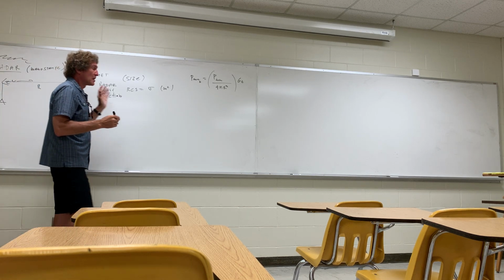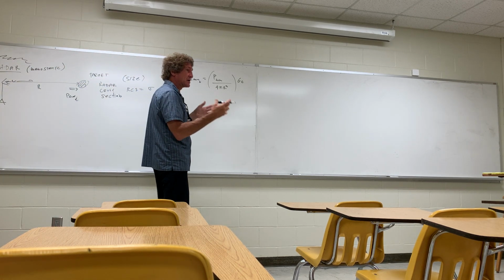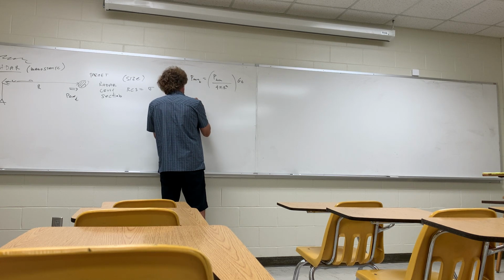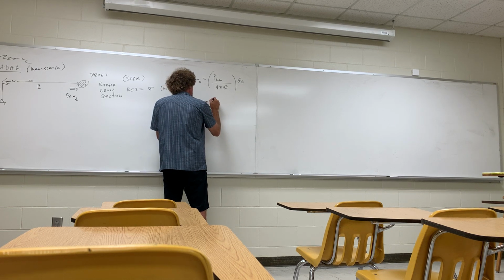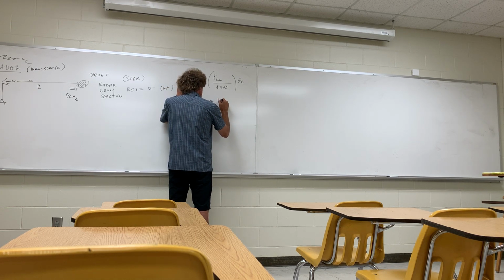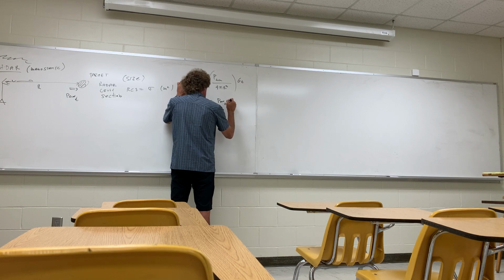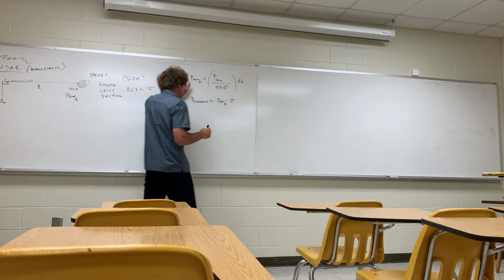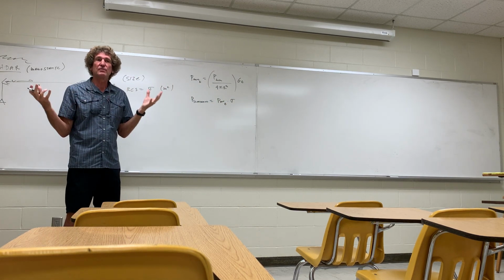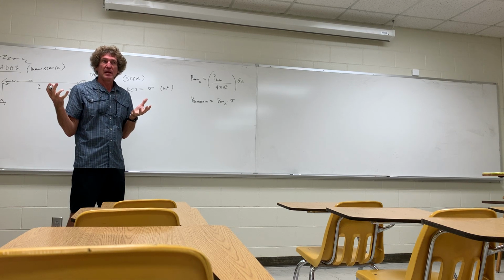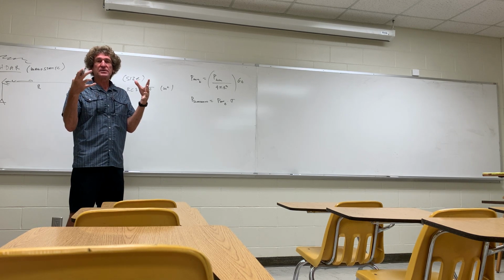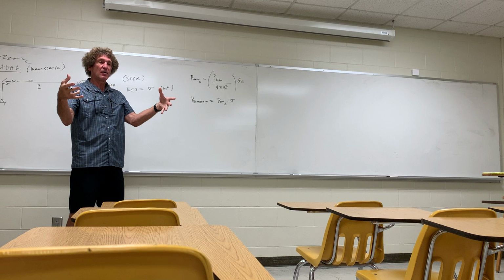Then the amount of power that's scattered by that target, I'll call it P scattered, is just P average on the target times the radar cross-section of the target. So now all that power is re-radiating, and as it re-radiates, it falls off as 1 over 4 pi r squared.